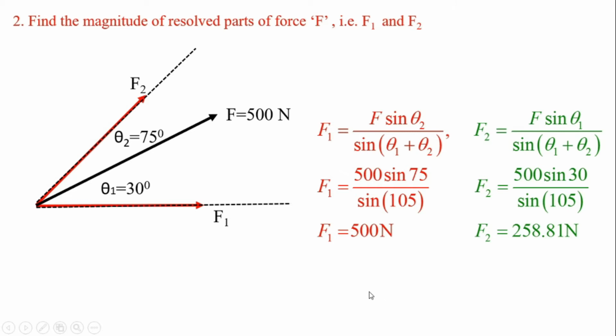So directly you can use the standard formulae and you can calculate the components. Remember, if force is to be resolved along two perpendicular directions, in that case we use Fx is equal to F cos theta and Fy is equal to F sin theta, but this is skew resolution and that is why we are using these two special equations. So this is the second problem. Resolve a force along two non-perpendicular directions, find F1 and F2. Problem is very simple.